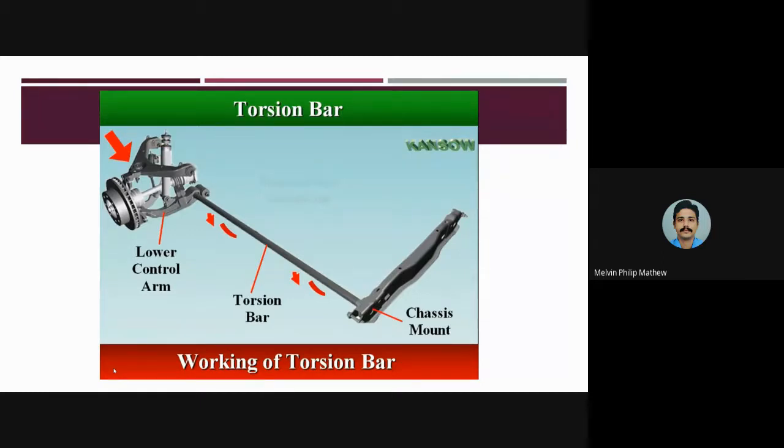works as the suspension system itself. It absorbs the torsion that is occurring. So in the suspension, the linear forces are taken by the coil spring or the telescopic suspension or the leaf spring. While in a torsion bar, the undesirable rotational forces are held inside the torsion bar. So it will twist under that load and then retwist by its own rigidness when that force is removed. So that is the function of a torsion bar.